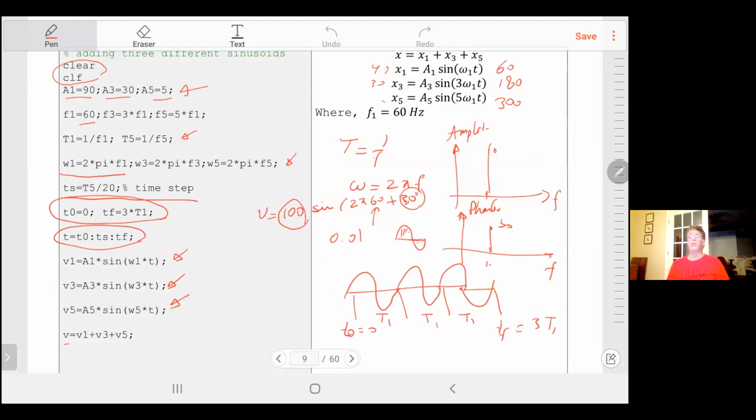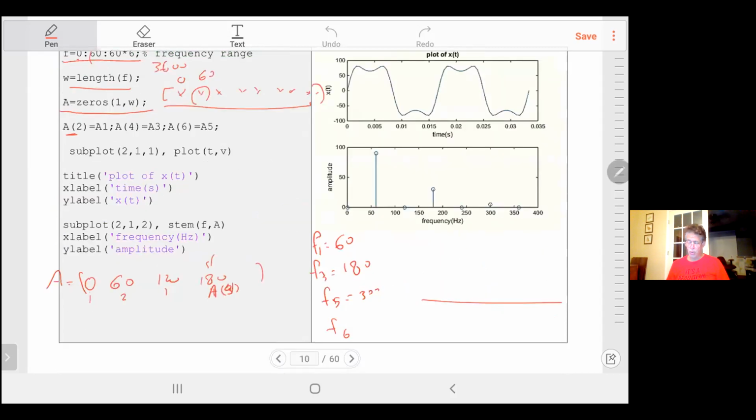And then after that, the fifth one, A5. When the frequency is 5 times the fundamental, the amplitude is equal to 5. We call it A5. You go there, you look for which one will be 5. You'll find that's equal to this. It's the sixth element because we start with 0, so 0 is not counted. So you add 1. That's in general. So at the sixth place in the vector A, you put A5, which is the amplitude of the fifth harmonic given. Now you are done.